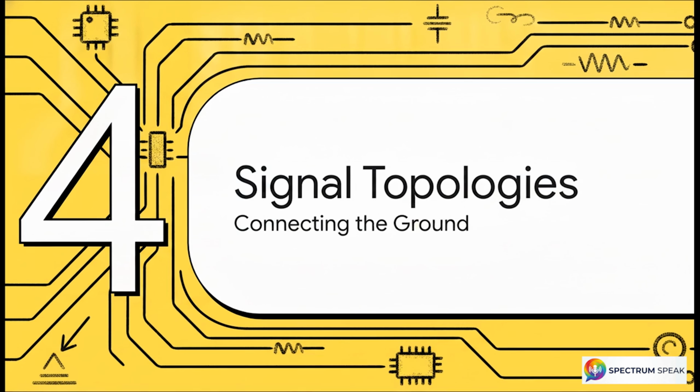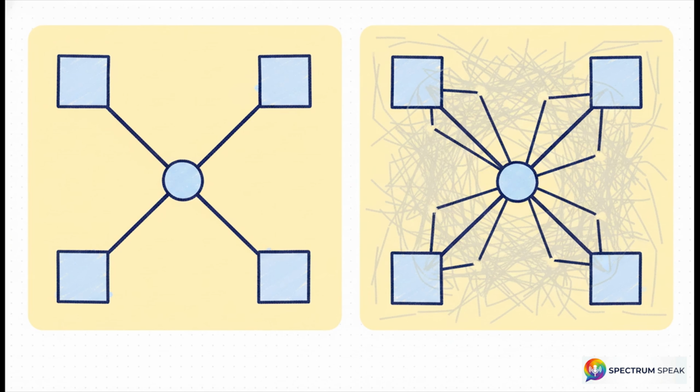Section 4. Signal grounding and topologies. Now let's shift gears and apply this math to practical signal grounding topologies for our electronic equipment. When wiring up systems, engineers generally choose between single-point grounds and multi-point grounds. Single-point grounding is great for low frequencies, but as your frequency increases, the stray capacitance between wires and the metal chassis starts acting like invisible short circuits. This basically forces our system into becoming a multi-point ground anyway, whether we want it to or not.